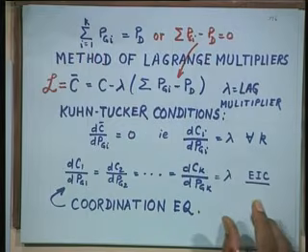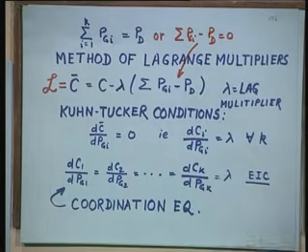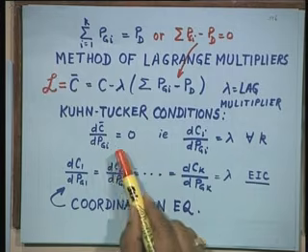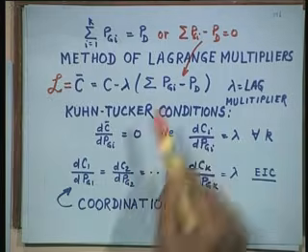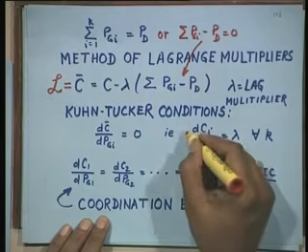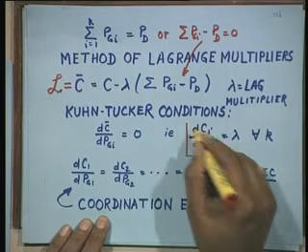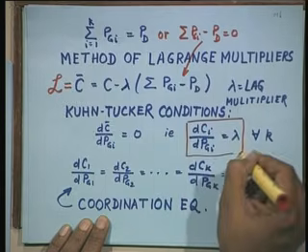Here, unfortunately or fortunately, we have only one variable Pg. So, that is u, the control. You have to control power generation. How do you control? By varying the steam input. So, only one derivative put equal to 0, and if you solve this you get the solution. It is such a simple problem.